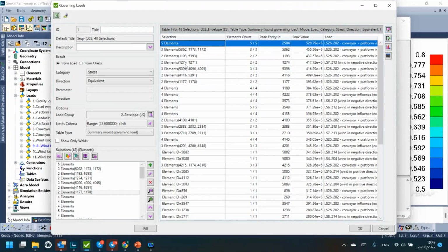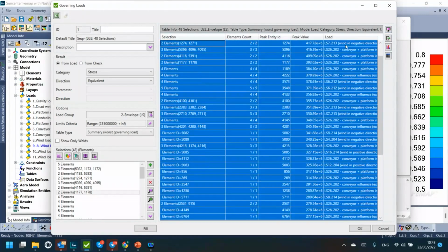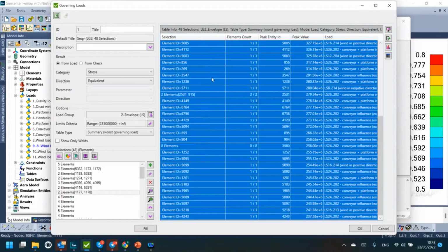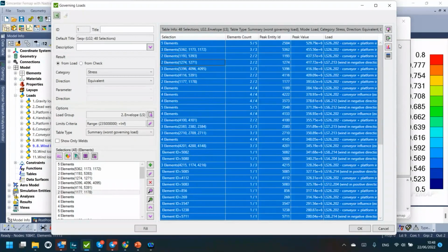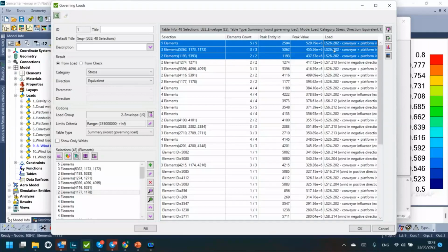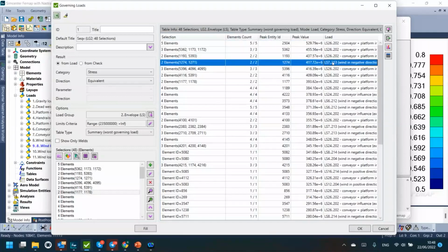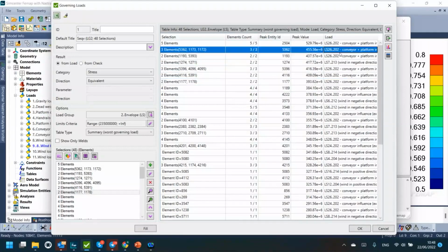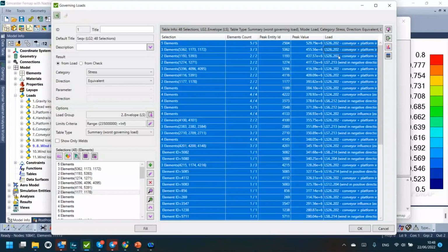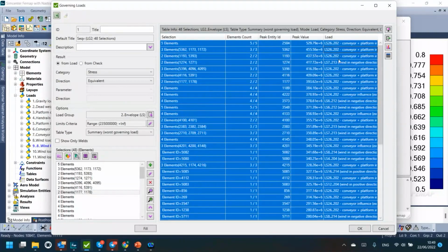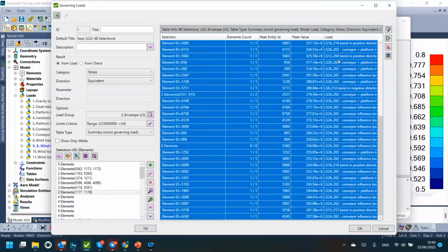Basically, what I can do here, I can export all these governing load situations which lead to the highest stress level per each zone in the load group. Yeah, so I see that I have load set 26 is causing the highest stress level at first 3 zones, load set 7 in another one, load set 26 in this 3 or 4, and so on. But I would like to store them all in a separate load group and keep as the governing one, because basically these load combinations are the governing in terms of the stress level. And this is what I'm gonna do.